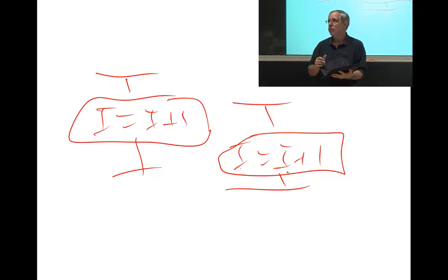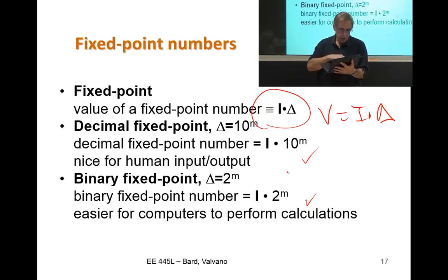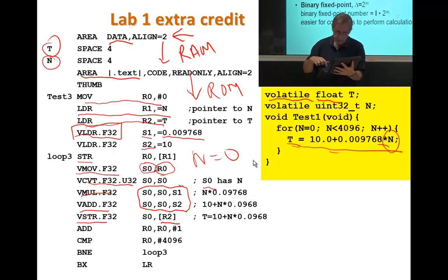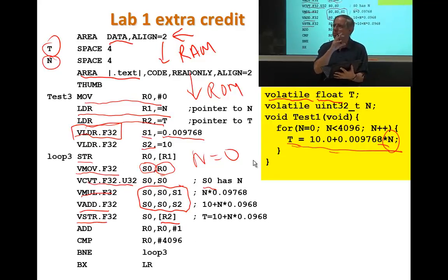Yeah. Is there any initialization needed before we use the S registers? No. Well, you're going to need to turn the floating point on, and you'll notice in all my examples, I've shut the floating point off, by the way. So you'll have to explicitly turn on the floating point with some opcodes, because I'm going to shut it all off so when an interrupt happens, it doesn't have to push 18 registers on the stack. But it's pretty well set up, I think.